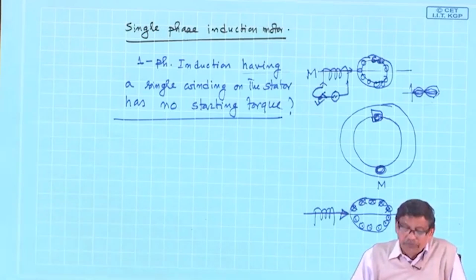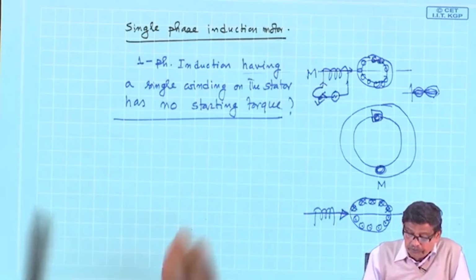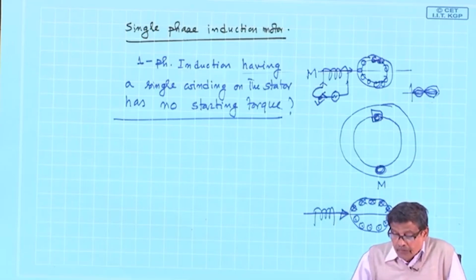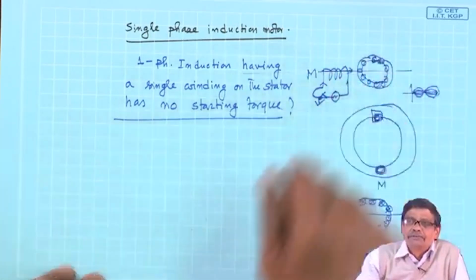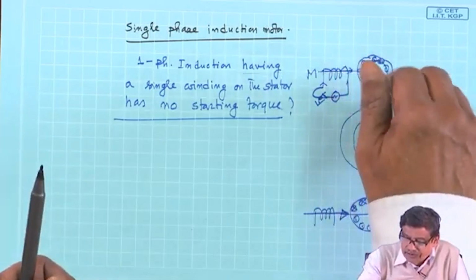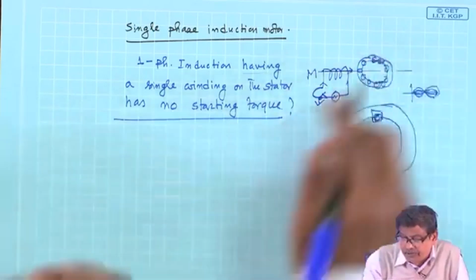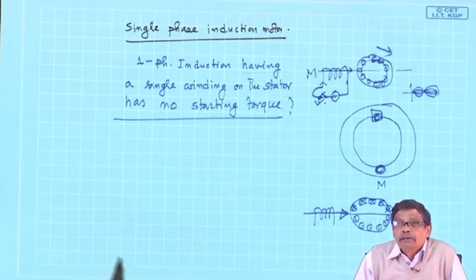So, it looks like the thing is nipped in the bud. Now, the idea is that a single phase induction motor, I will show that although it has no starting torque, suppose by hand you make it run, with some prime mover you give a sufficient start. By some external agency, if you start moving the rotor with this supply on, you will find to your surprise the machine is picking up speed and will settle down to some final speed.